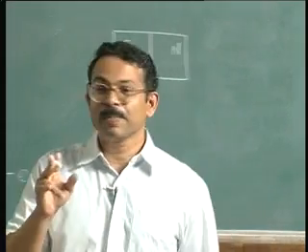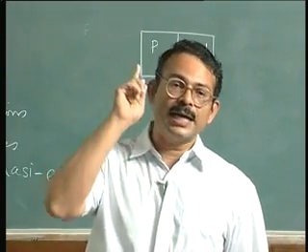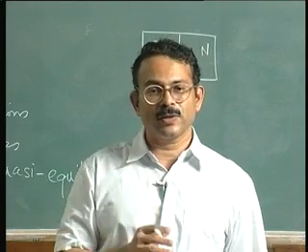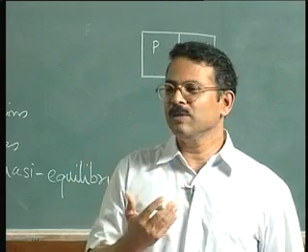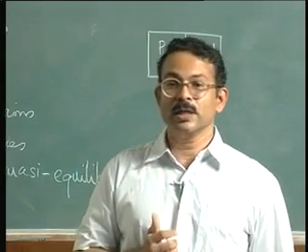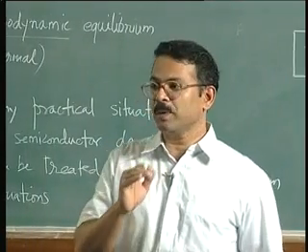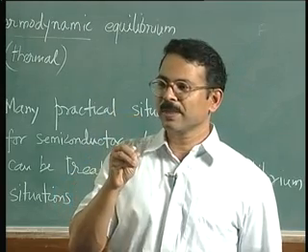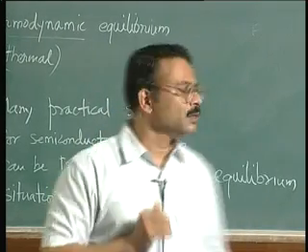It does not say no motion of charge and energy. This is very important. No net motion, the word net is very important. So it is a very dynamic situation in which there is intense activity but which is not in any one direction. This is the reason why this condition is a useful starting point, because now if you add any other excitations then we can treat this condition as a small deviation from equilibrium condition.